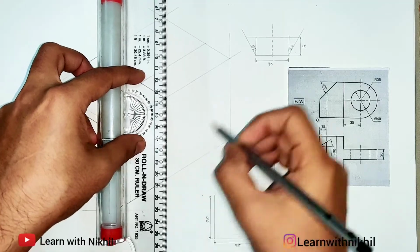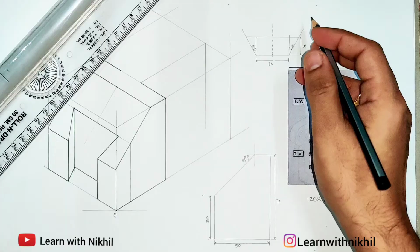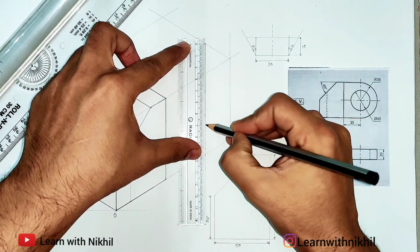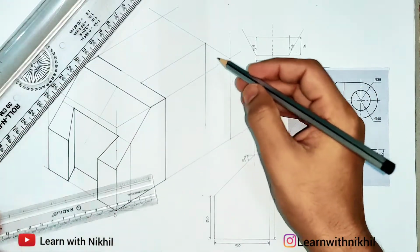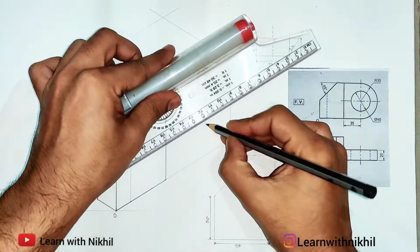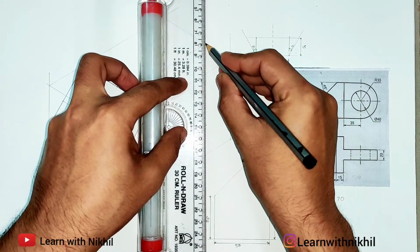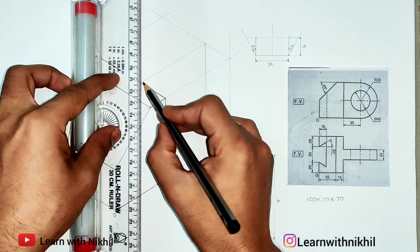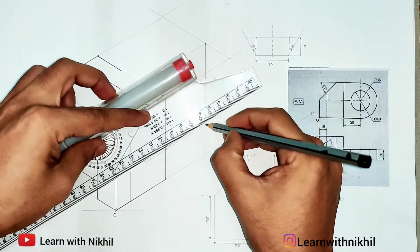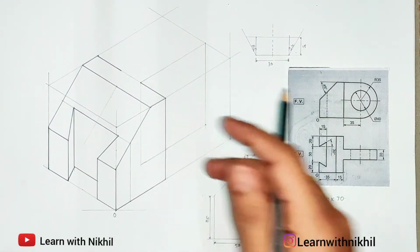Now taking this as a reference line, from here 70 millimeter below, marking, then drawing a parallel line from here 70 millimeters on the left side, taking this as the parallel line, and from here 70 millimeters below. So this is the whole rectangular or square box of side 70 millimeter. Draw it lightly.